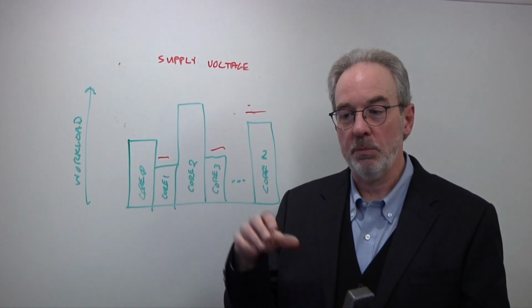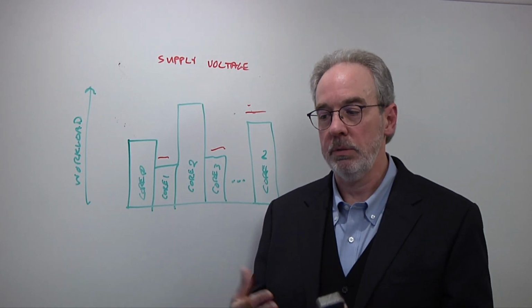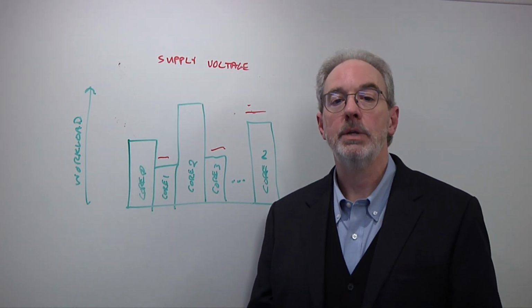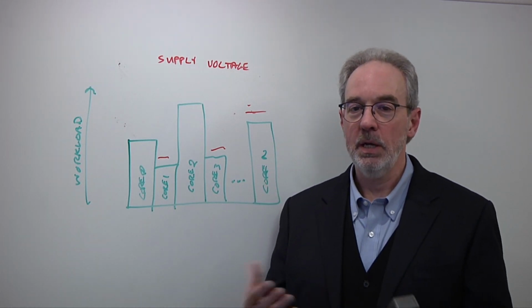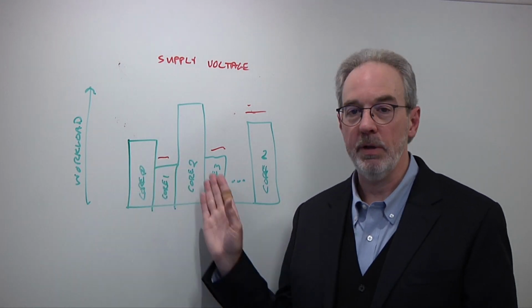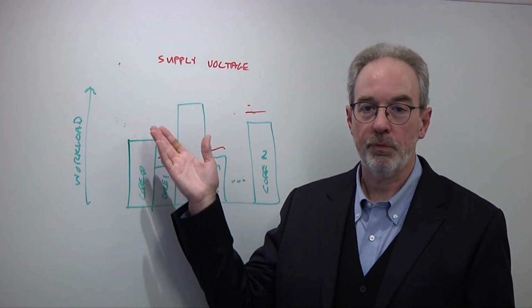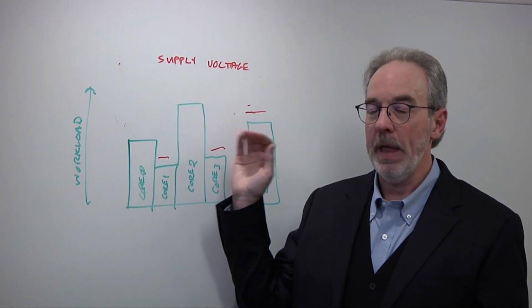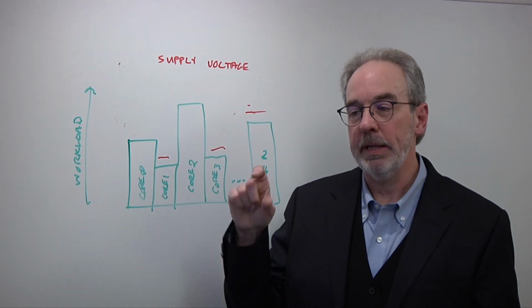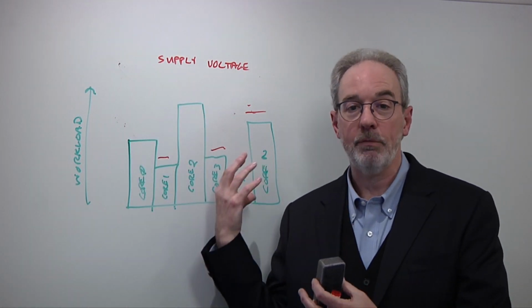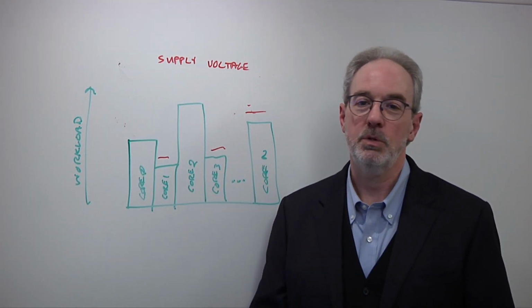So we're seeing more and more customers at that ragged edge of what they're doing, where they're designing a system to work most of the time, and then they're deploying droop mitigation or other techniques to catch those excursions and to be able to respond, whether that's through DVFS or droop mitigation, the frequency, whatever you do. That has to be a part of the design, and that's done at the very beginning where you design that flexibility in, because it's really difficult to do later.